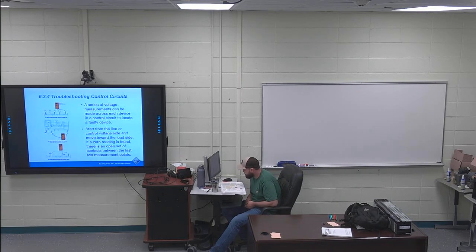On page 55, that paragraph that's continued over from 54, if you look directly to the right of the troubleshooting safety on page 54, where it says figure 38, I've got that sentence highlighted. As shown in figure 38, a reading of 0 ohms indicates a shorted coil, and a reading of infinite resistance indicates an open coil.